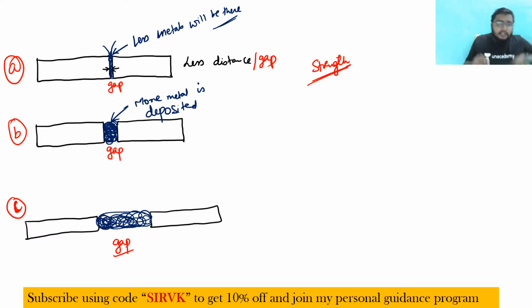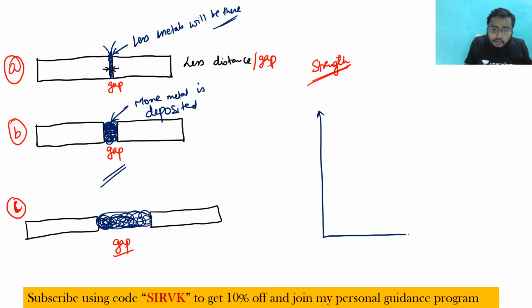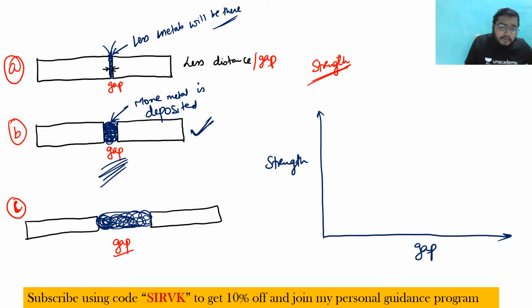If you give not a very big gap like this, but a good gap, that is an optimum gap, then we get a very good amount of weld. So what I'm trying to say is, if I plot gap versus strength, the strength of this kind of welding would be more. Why more? Because metal is deposited in a very good quantity, and the gap is neither very big nor very small. It is an optimum gap.